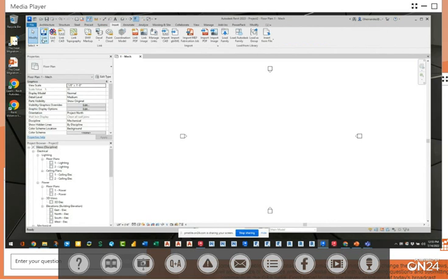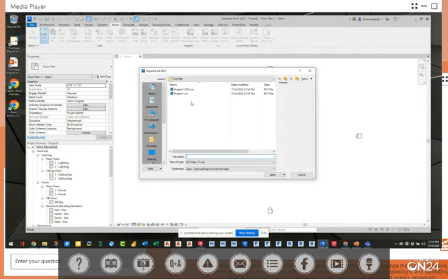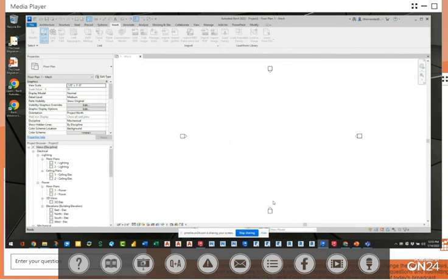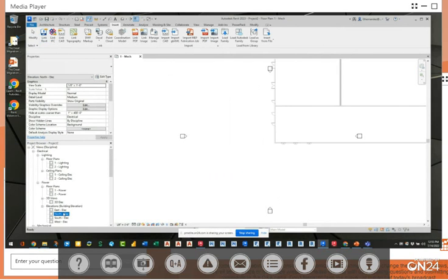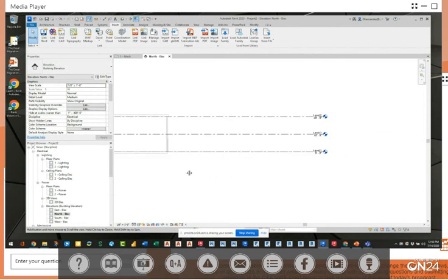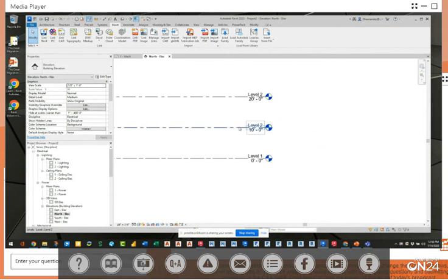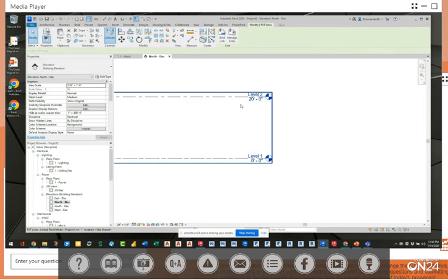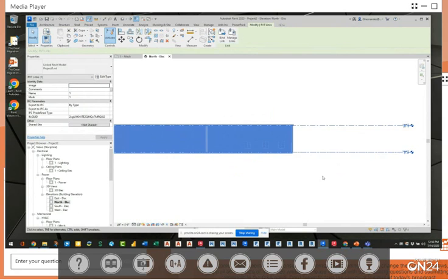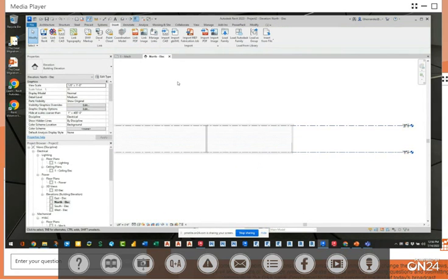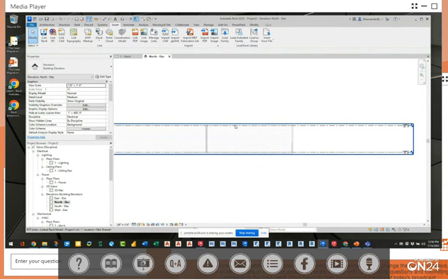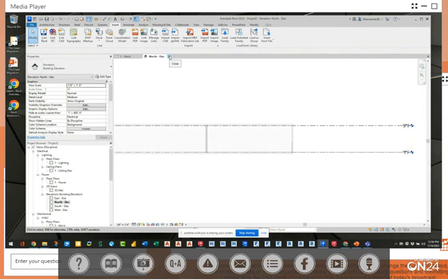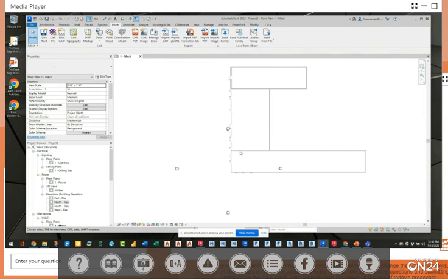You would link in or XREF in the architectural background. Again, remember, getting the positioning is super important. And now in my mechanical templates or MEP templates, there's my project defined in the background, right? As the designers, it makes all the difference setting this up early on and not moving it around. Okay, so keep that in mind.